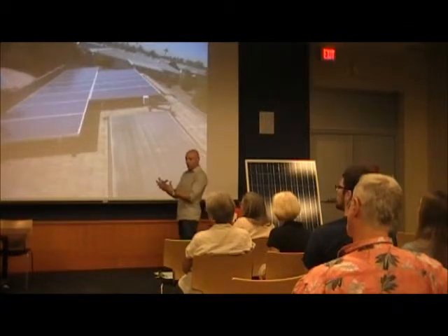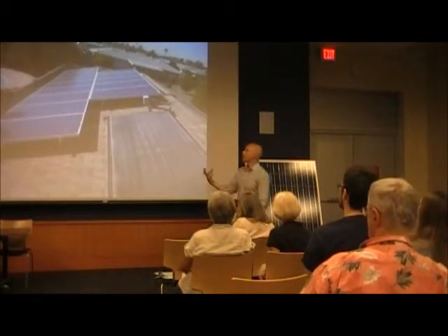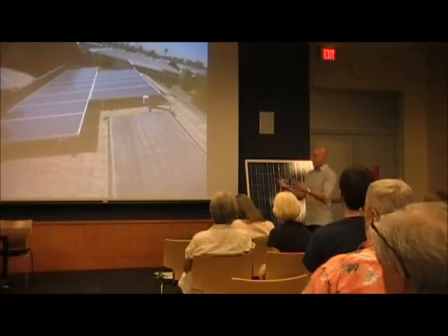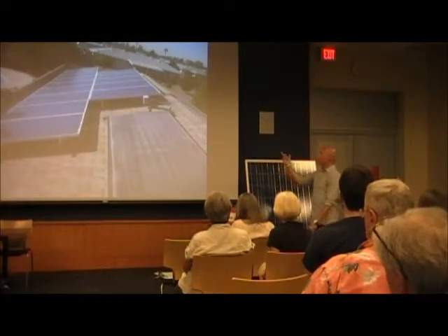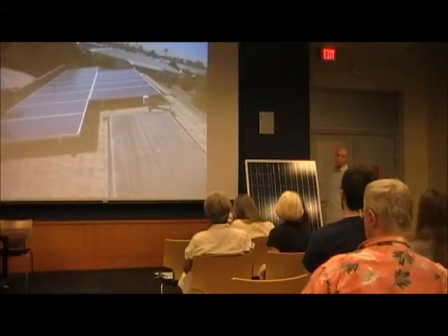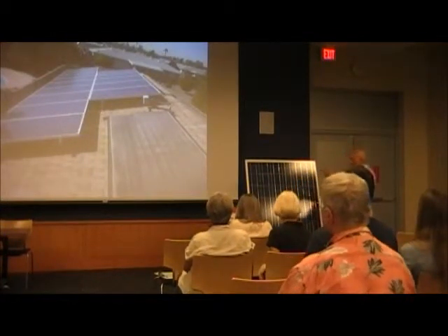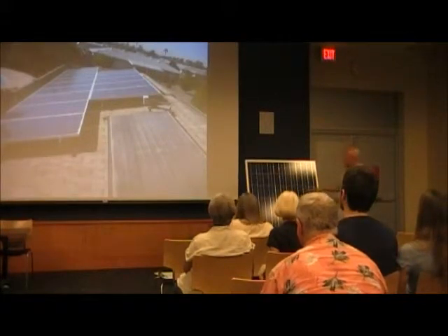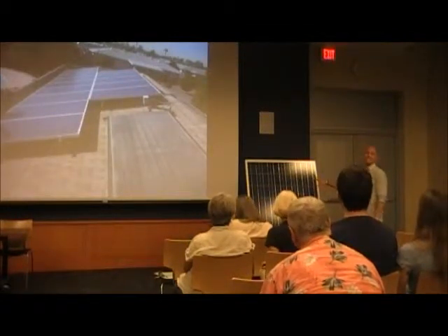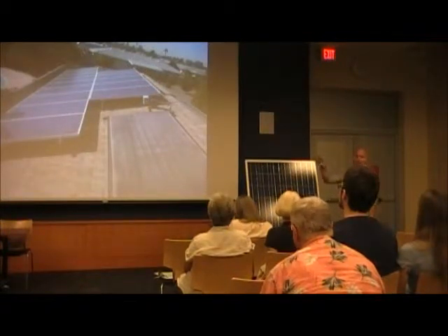You can have small microinverters that fit behind each module, and that will make each module its own AC module. But you've got a lot more inverters, so a little more expense in cost as well as install. If you install just one of these, it's not a big deal. But we just did a job the other day with 160 little inverters behind 160 modules, so it takes a little longer. Instead of just plugging the modules together, you have to hook up the little inverter that sits right behind, plug all that in, and ground it. It's a lot more. But if you're in an area that gives a great incentive, or an area with a lot of sunlight, like the Southwest, it might be worth that extra. Especially if you're paying more for your energy costs too.